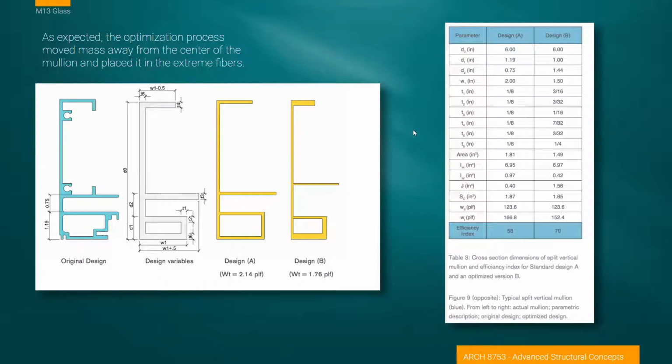And we can take that to the development of our extrusion. So in our curtain wall extrusion, we came up with a relatively standard shape. But there's a lot of thinking towards the way we can use generative design and even just skilled design to remove the mass, as much aluminum as possible, from where it is not doing effective work, and put it in places where it can do. So here we have a higher performing design, if we were to look at design A to design B, just to illustrate this a little bit, design B being stronger but lightweight.